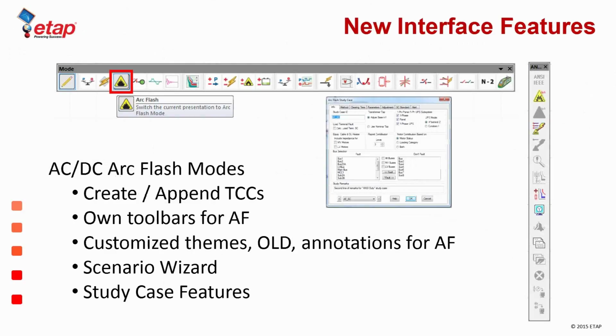So the first thing I'd like to bring up is the new interface features in ETAP 14. The first thing you will notice when you launch ETAP 14 is that Arc Flash now has its own independent study mode. So Arc Flash is no longer nested under short circuit analysis.